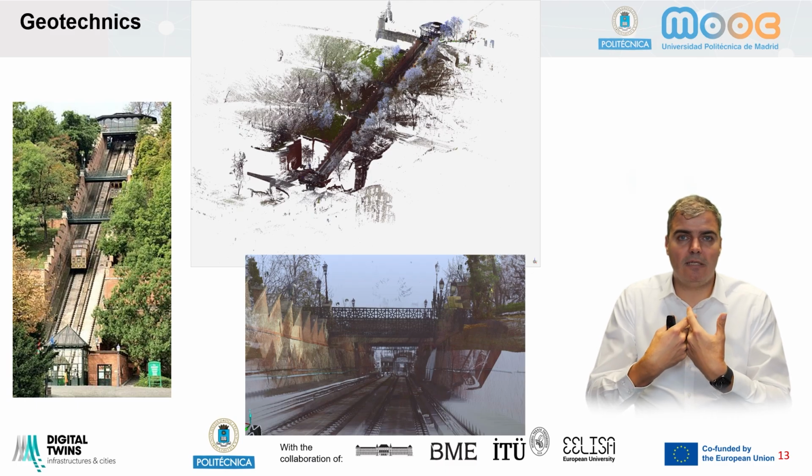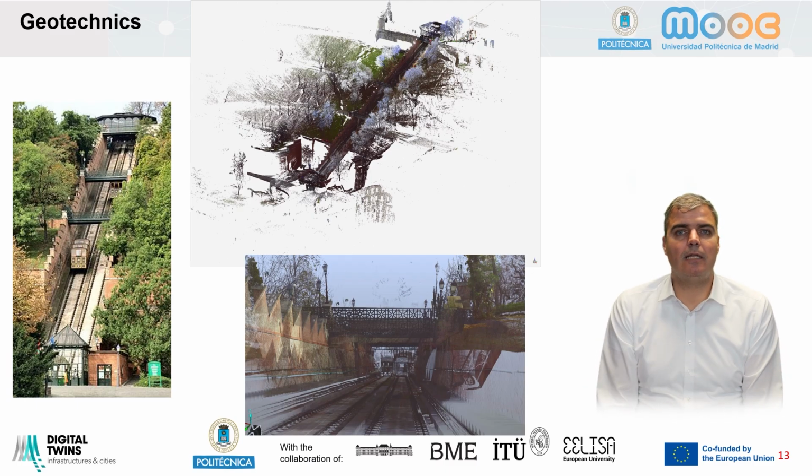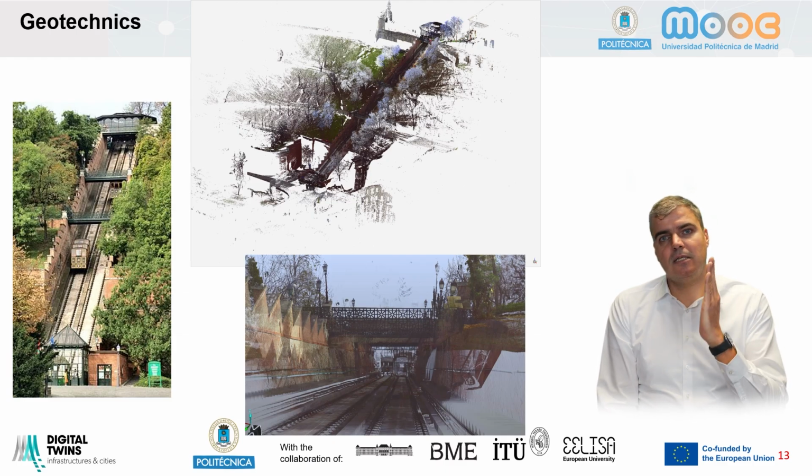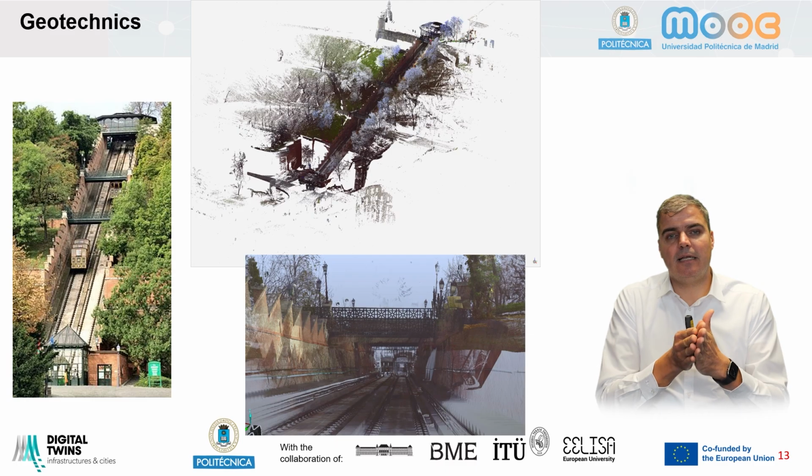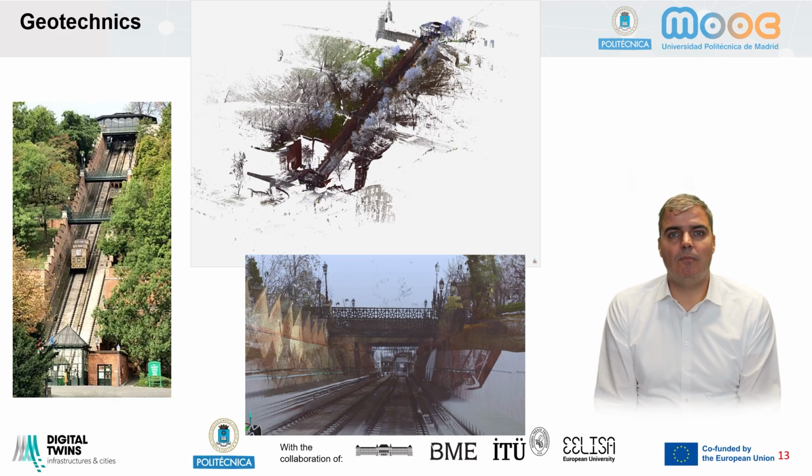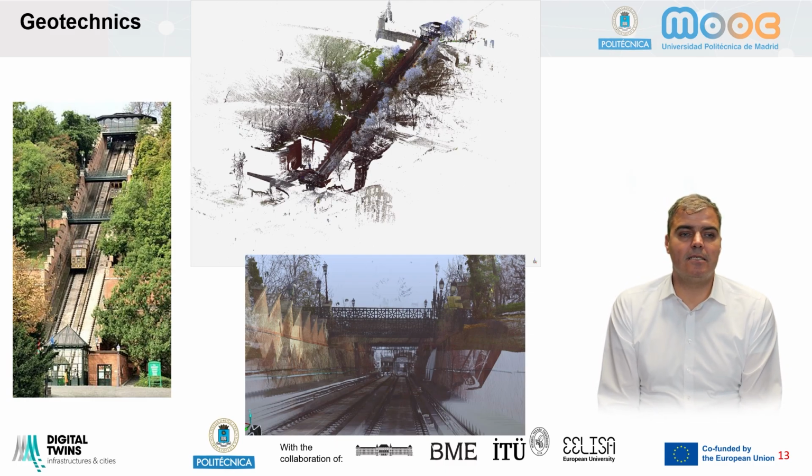They wanted to capture entire geometry. So that's why the final solution was laser scanning. So we laser scanned the entire wall sections and projected ideal planes and created the deviation maps compared to the ideal planes, and we derived where are the biggest differences, and then the geotechnical experts could make their surveys.